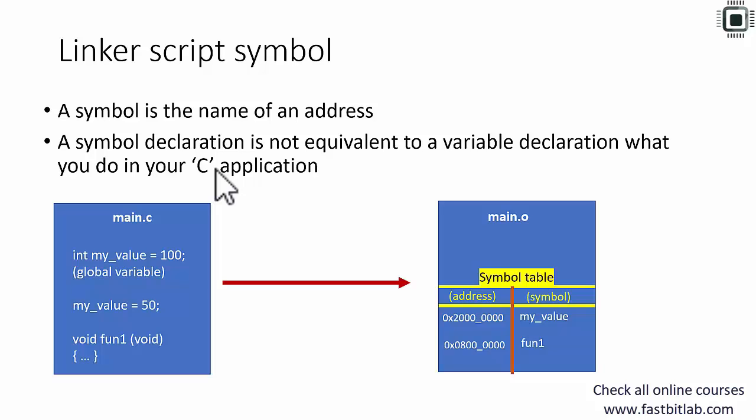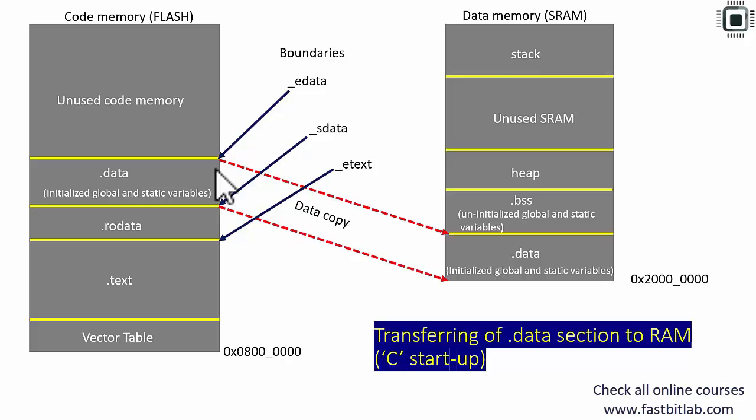Now the scenario is different. We have to worry about creating some symbols because we are writing the linker script. And inside the linker script, we want to catch this boundary information. How do you store the boundary information? Would you create variables? No, you can't, because we are not writing any .c file which is going to be compiled by the C compiler, isn't it?